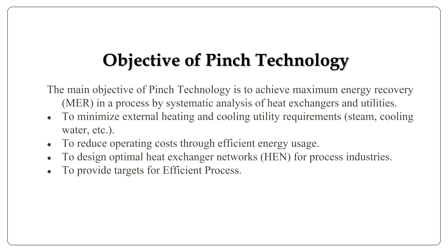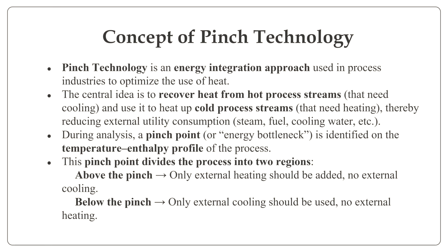The objective of pinch technology is to achieve the maximum energy recovery by systematic analysis of heat exchangers and utilities. By minimizing external utilities like heating and cooling requirements, we can achieve the maximum energy recovery. Also, we can reduce operating cost through efficient energy usage, and designing an optimal heat exchanging network also increases the efficiency of the process and provides the target for the energy integration process.